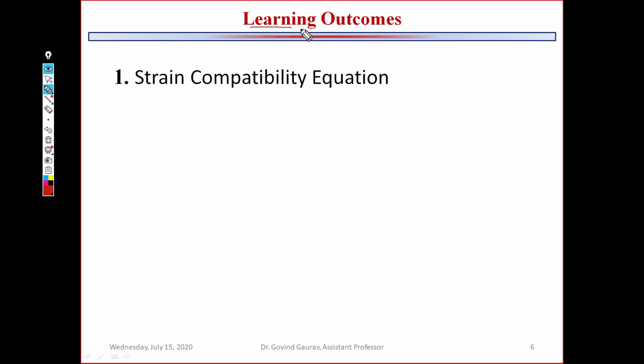So the learning outcomes of this session are: we have derived the 6 different strain compatibility equations. Apart from the other sets of equations, which are the equilibrium equations, these 6 sets of strain compatibility equations also need to be satisfied.